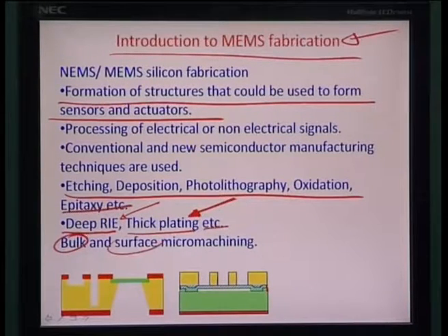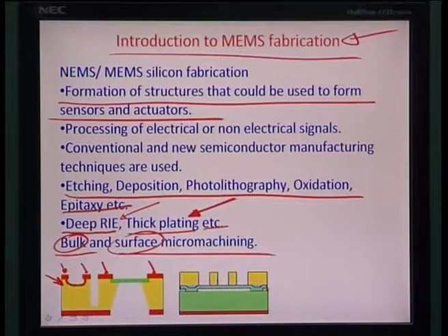And really if you divide this whole machining, you can categorize them into bulk and surface micromachining. The bulk, as you know, is more related to the volume removal or the bulk removal of the material. This right here is an illustration. So this is the cross section of the silicon wafer, and you can use this particular red layer here as the masking layer, and you can actually etch away material underneath it using an etching solution homogeneously or isotropically. Or you could actually do a deep RIE based etch, where you can have very straight aspect ratio or geometry of this particular channel.